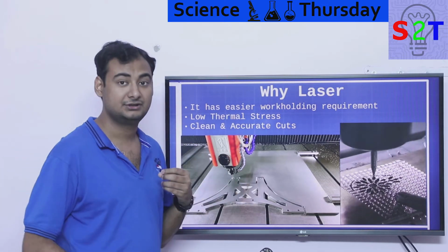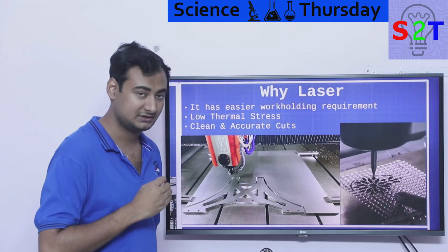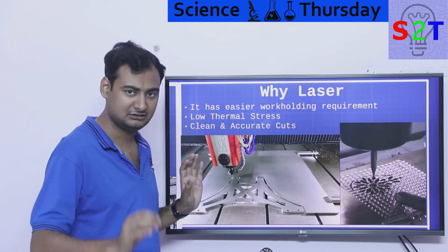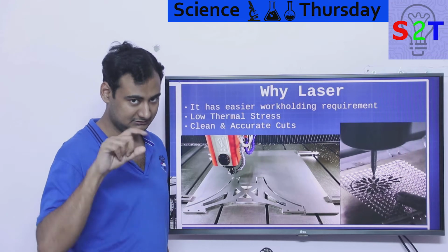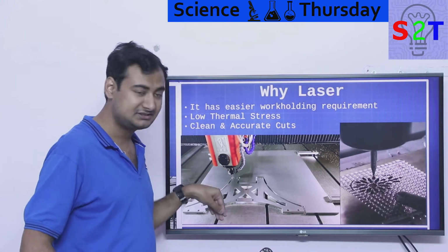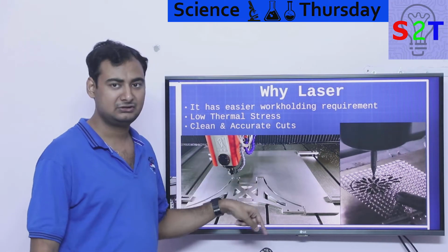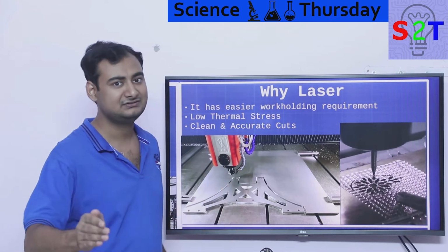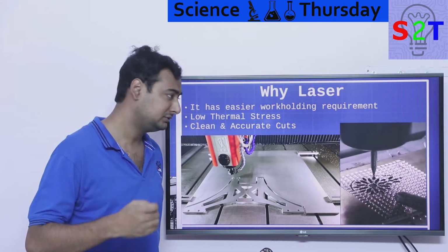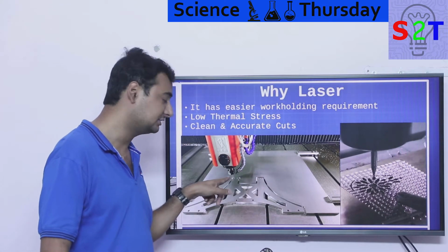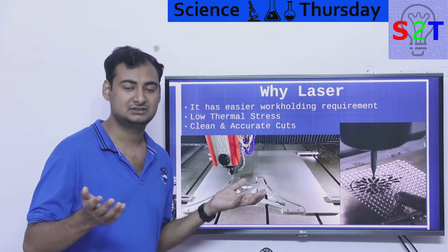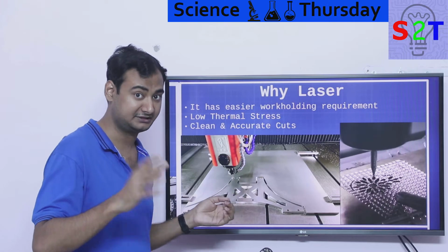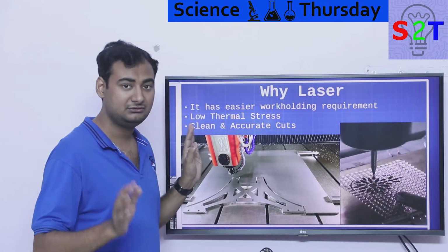And not to mention, we also want to reduce what we classify as thermal stress, because even if you have the latest and greatest spindle motor and the latest and greatest mill doing the actual grinding, it will still heat up the material. Now again, it will not be an issue for one, but if you are doing hundreds of these, it will become an issue. And not only for the material that you are cutting, but also for the drill bit, which will not last if it heats up too much. You can easily see many CNC machines come with liquid coolant running directly, so you can understand we want to minimize that.